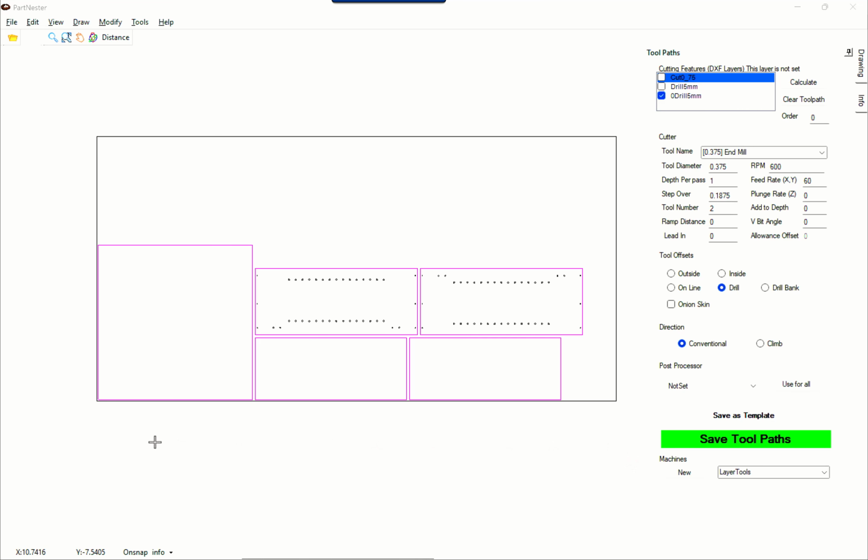Most machines have XY0 set to the lower left corner of the machine. So with it being set to the lower left, X moves to the right in a positive motion. The Y moves up in a positive motion. While that is common in most machines, there are few out there that have the 0,0 origin or the home origin to the upper left and upper right.